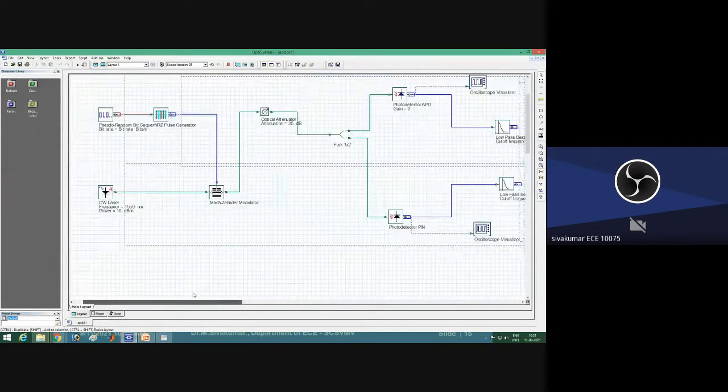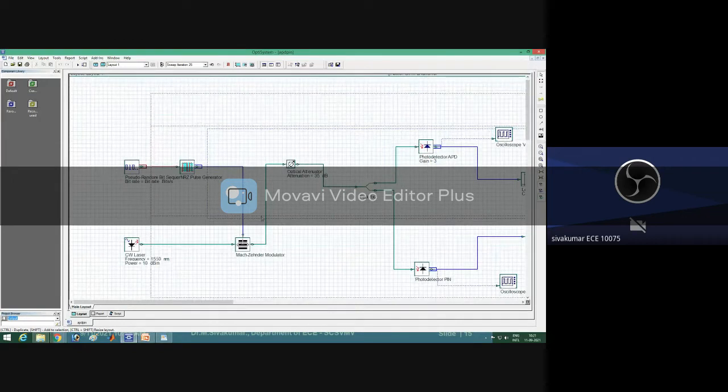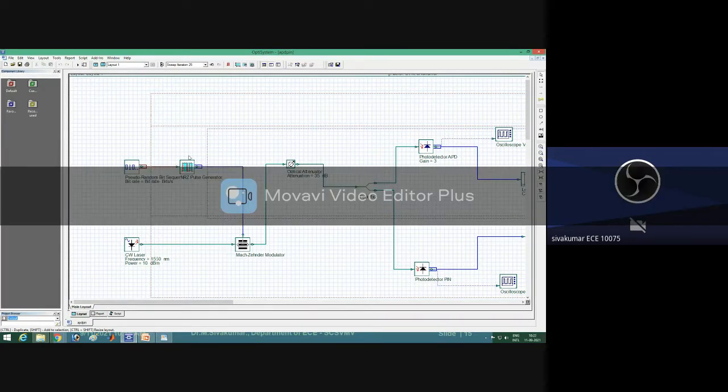These are as per the PPT. These are all on the transmitter side. The optical transmitter has 4 subsystems. What is the first subsystem? It is a PRBS sequence generator. These are input bits, and the output of this PRBS sequence generator is applied to the pulse generator. Here in this example, we use an NRZ pulse generator.